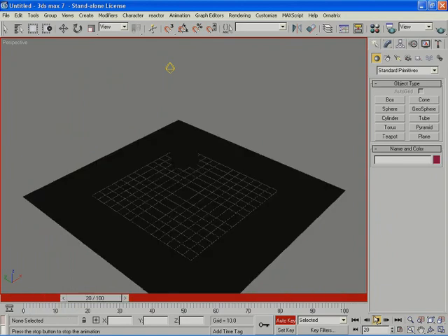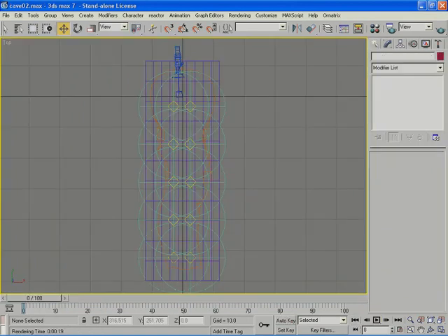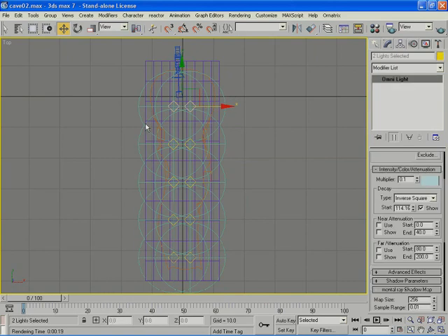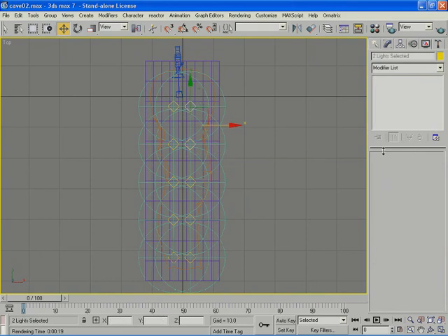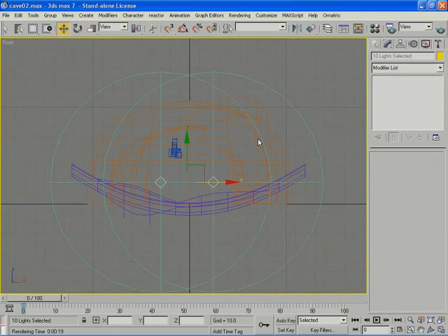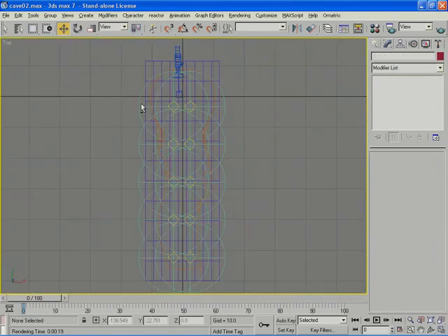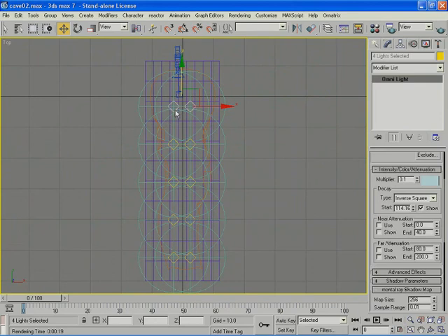Whenever two lights are instances of each other, when you select them both, you're going to see the parameters of both, so we can change. But if I grab these two, they're not instances, so I cannot see the parameters. So here, these 4 are instances together, and these 4, and so forth. But these 8 are not instances together. So 4 by 4, I have instances here.